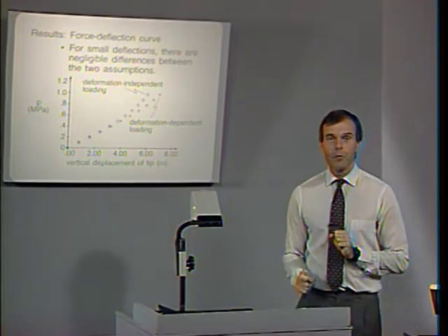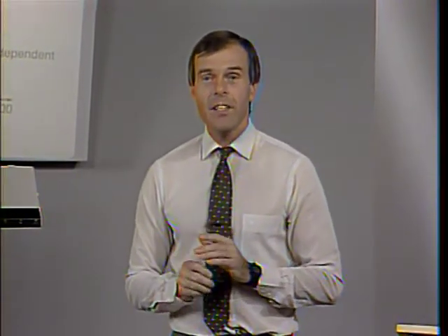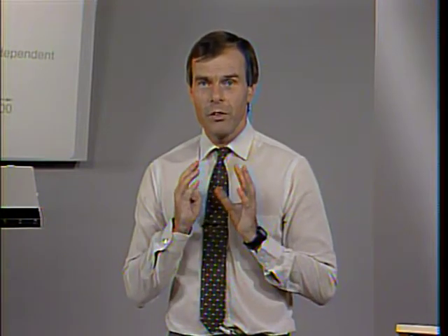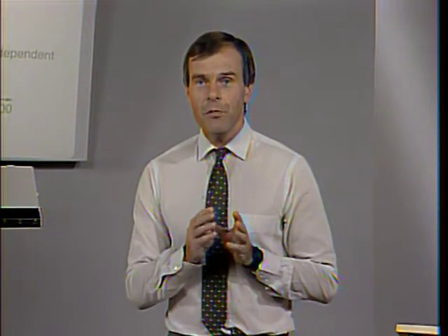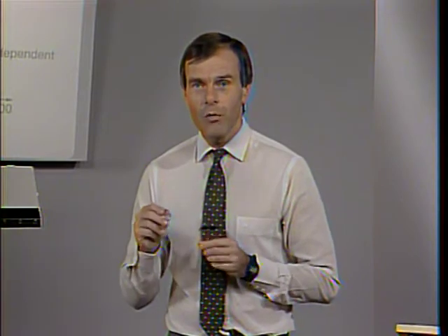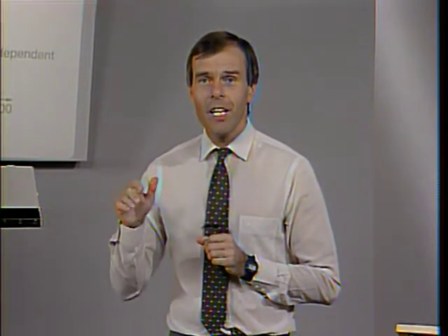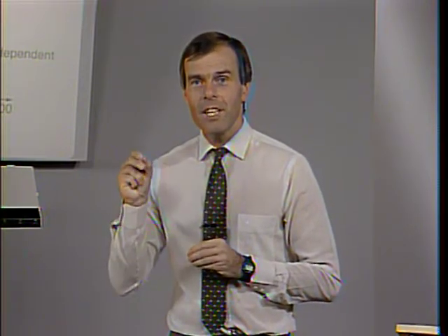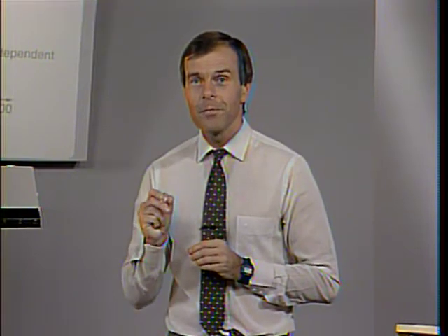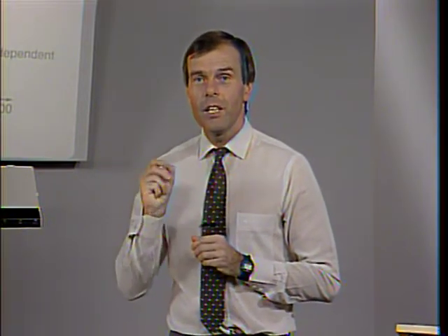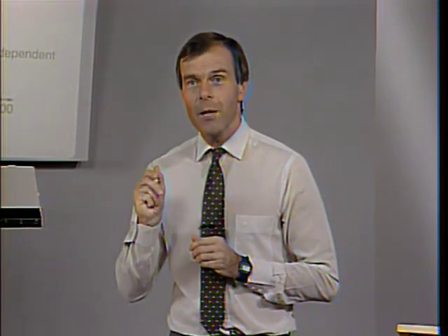I should add here, if we look back at what we discussed in our earlier lectures, that regarding the solution for the deformation-dependent loading case, we used a stiffness matrix that is symmetric, the same stiffness matrix, as a matter of fact, that we're usually using when we are analyzing deformation-independent loading. The deformation dependency of the loading was only taken into account by updating the right-hand side load vector t plus delta tr. In our earlier discussions, we very largely assumed that t plus delta tr is constant and prescribed by the analyst. But I also pointed out in the earlier lectures that if we have deformation-dependent loading, we would have a t plus delta tr superscript I minus 1, where that I minus 1 then refers to the configuration corresponding to the end of the I minus first iteration.